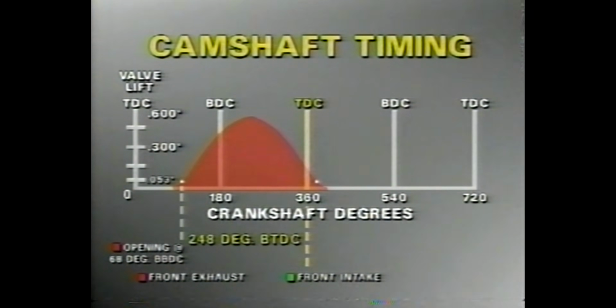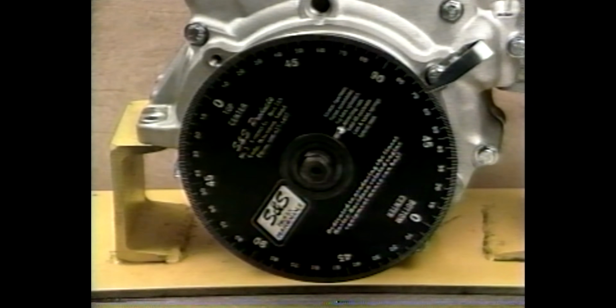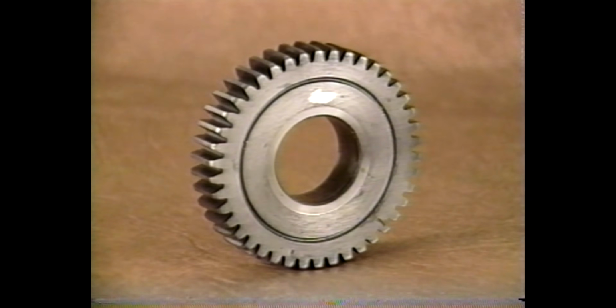To avoid any errors due to backlash in the gear train, we make sure that we rotate the crankshaft in one direction only. Please note that we have removed the cam drive gear solely for demonstration purposes.